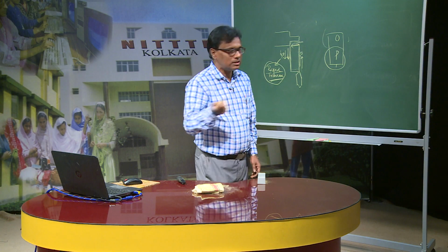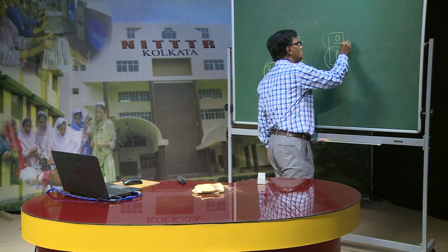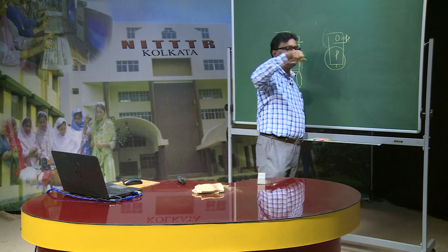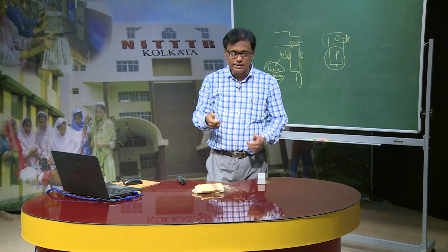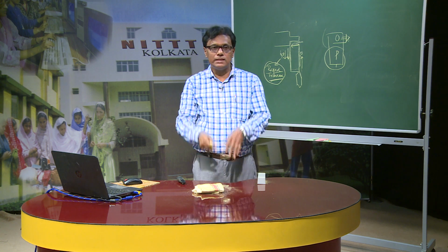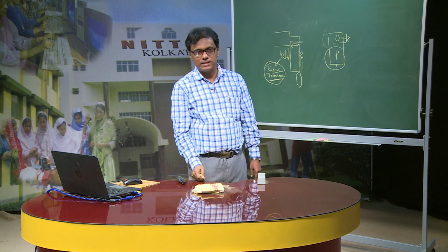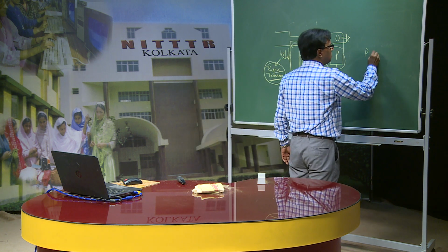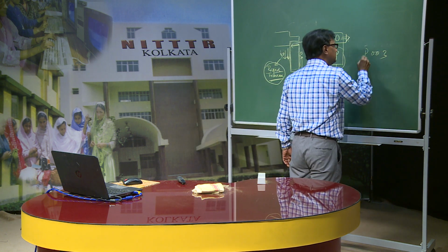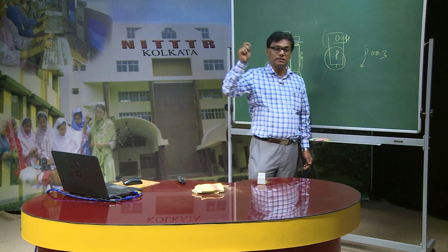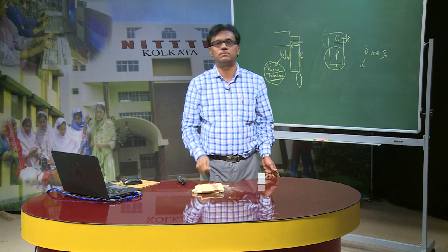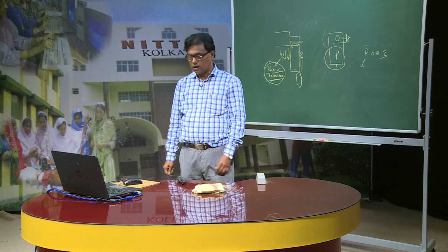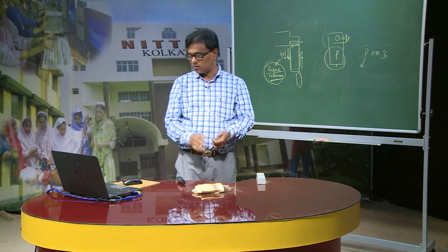If a program starts with O, then you can be sure that this program is written on the basis of a Fanuc based control system. If it starts with P, like P0003, then you can be sure that this program is written for a Siemens controller system.